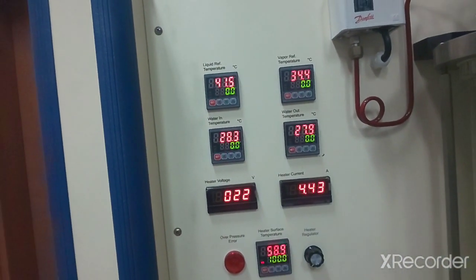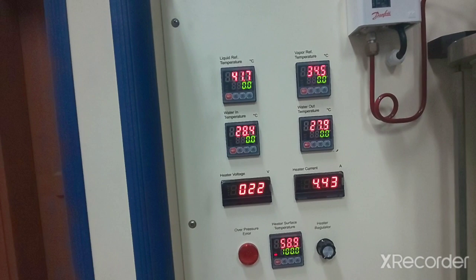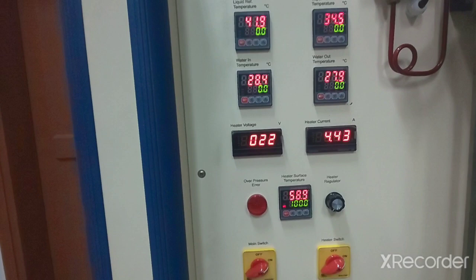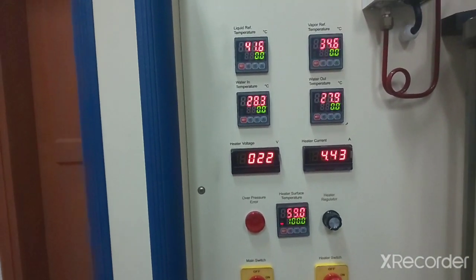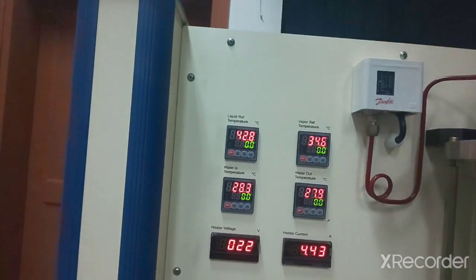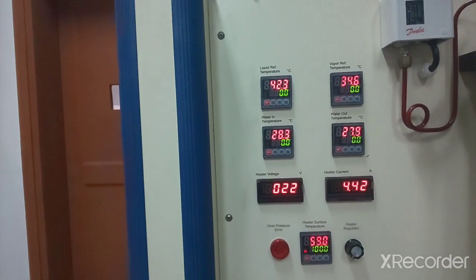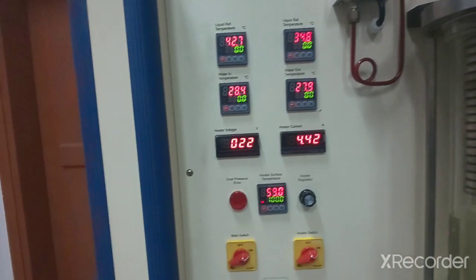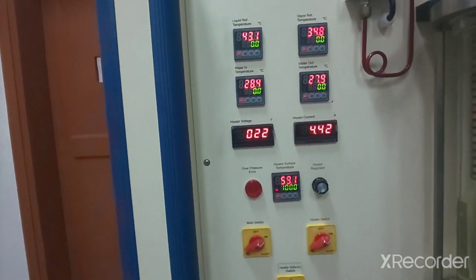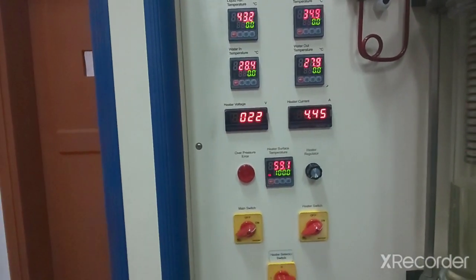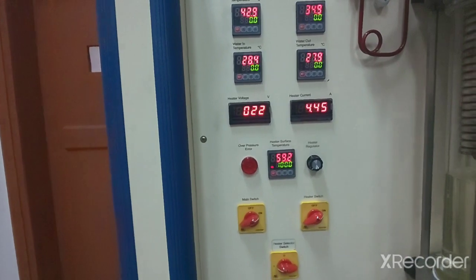There is one more thing: since we are taking temperature differences, we don't need to differentiate between the Kelvin scale and the Celsius scale. If you want to take the reading in Kelvin or Celsius, that is up to you. Right now the temperature of the refrigerant is still going up, so we will wait for that and then take out these readings. When it becomes stable, we will change the heater input again, and again take the values, and we will repeat it at least 5 times.